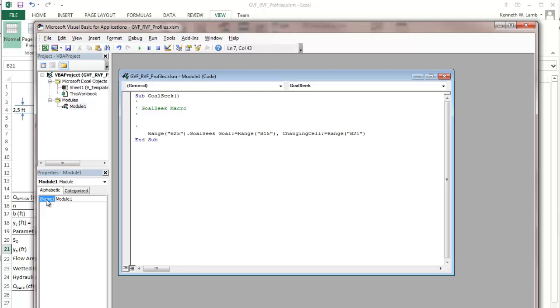The second edit we want to make is to copy and paste the single line of code. We want to run this command a total of 4 times because we have 4 different channel sections. So I highlight the line of code and then paste it for a total of 4 times. After copying the code, we modify the column reference in each one of these so that it moves to each new calculation. So the next row down would be C, and then D, and then E. Then we do the same thing for the last cell reference on the end. C, and then D, and then E.